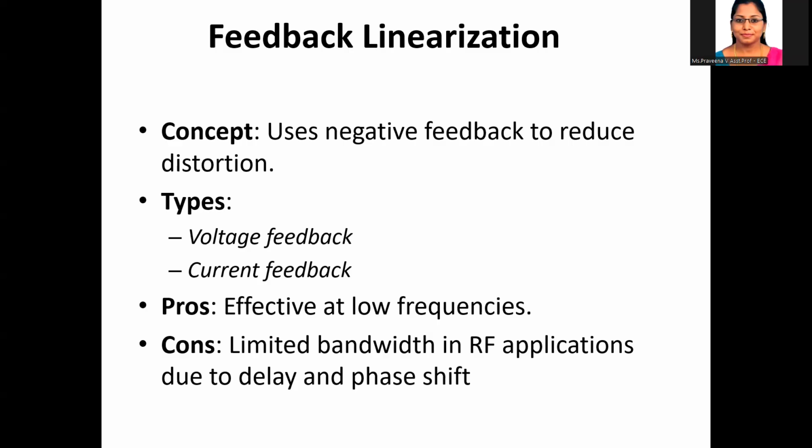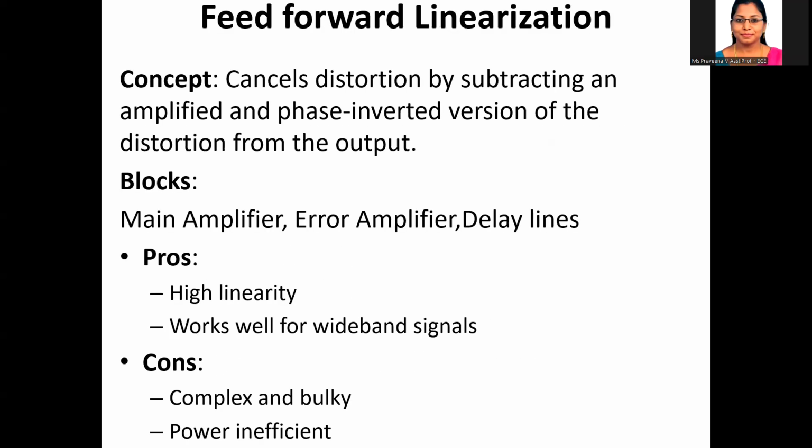The advantages are that it reduces harmonic distortion and stabilizes the gain. The disadvantage is limited bandwidth at RF frequencies due to delay and phase shift.